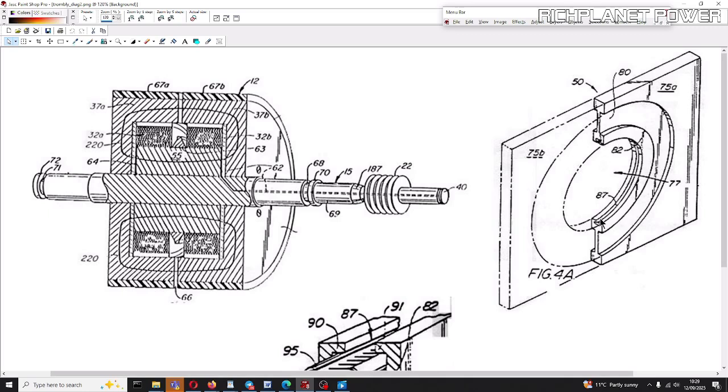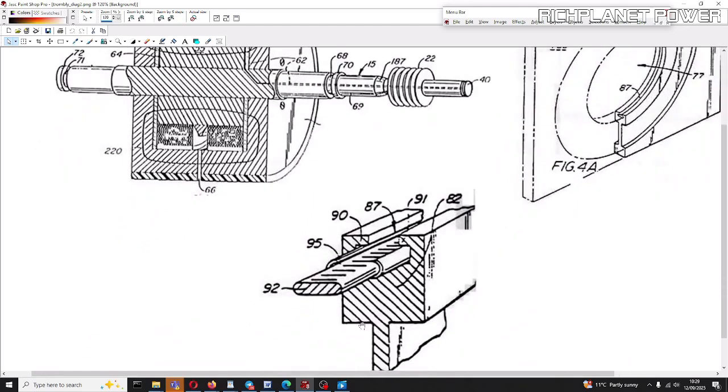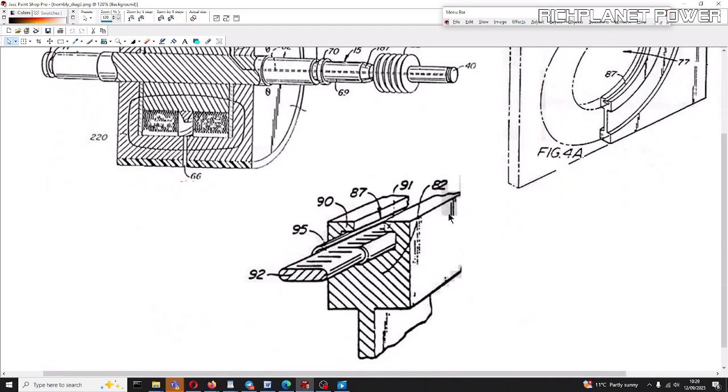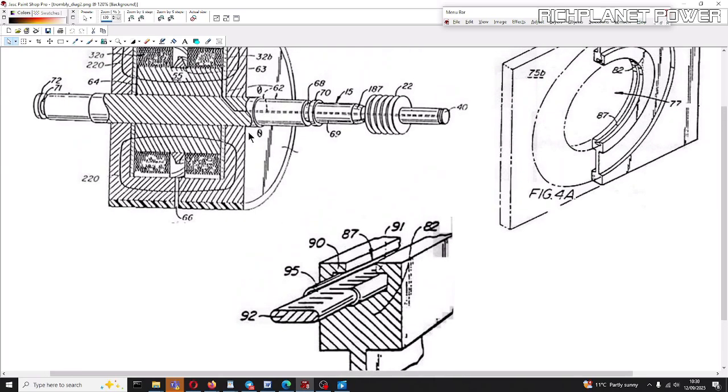So this rim here, this is an exploded view of it, right? So you see here we've got copper braid, and this is copper as well around it, and then your contact, which is moving, so this remains still, your contact which is moving sits in there, and it's then wetted with this liquid metal material. So there's very little contact between the actual disc, which the edge of it is there, and this braided material, and what makes the contact is the liquid metal, which will be sitting inside here.